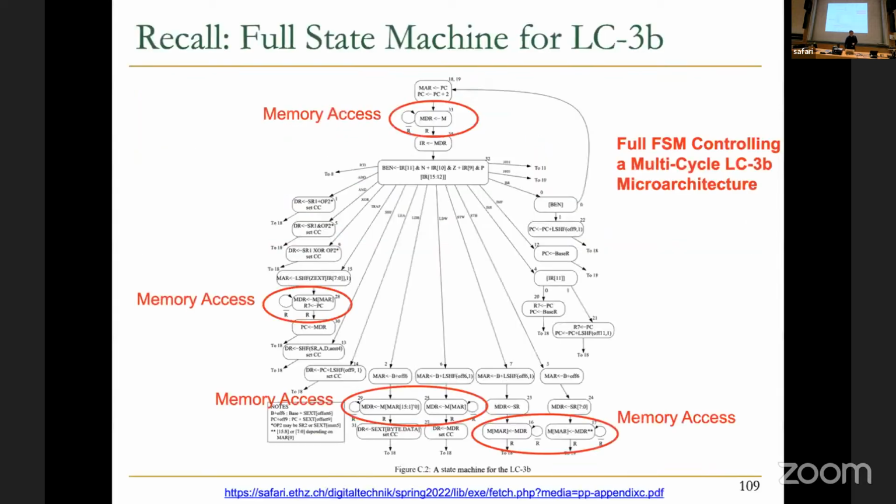But let me foreshadow memory by saying that these are the bottlenecks in today's systems, because memory takes long. You can see that the addition is 1 cycle, right? You don't wait until the addition. You could also do that. If any state needs more time, if the adder, multiplier, square root, divider, whatever you have in the instruction set takes longer, you can stay in that state for some time.